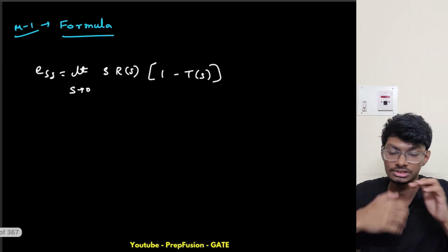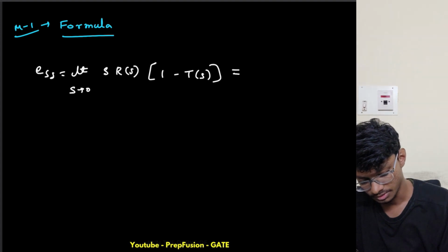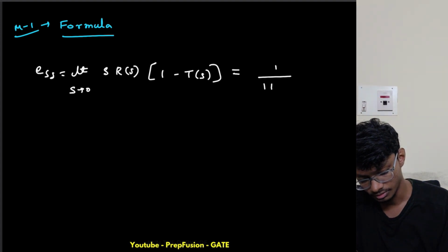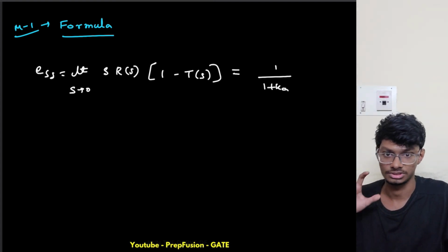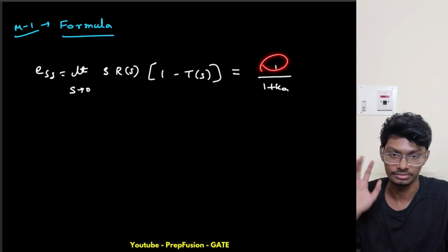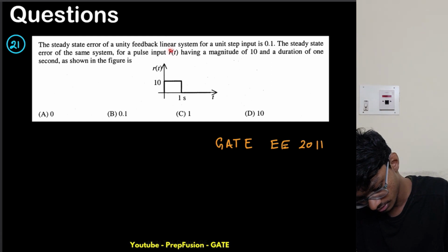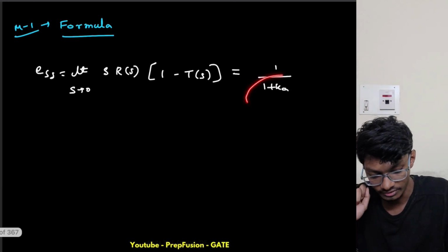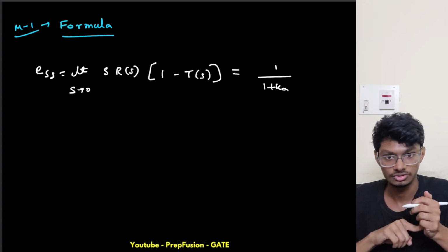We can do this in terms of the error coefficient also, right? So this will be equals to simply 1 upon 1 plus K for a unit step input. But if the step wasn't unit, if it was some other value, I would have to multiply by some other value here, right? This was unit step only, that is fine. So I can find my K from here. And what is K? K is basically g of 0.